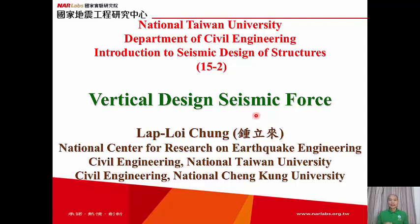In ground motion, there are three components. They are east-west direction, north-south direction, and vertical direction. From the east-west and north-south components of the ground motion, horizontal seismic force is induced. And vertical seismic force is induced by the vertical component of the ground motion. In this lecture, we will talk about the vertical design seismic force. That's the seismic force in the vertical component for the design of the structures.